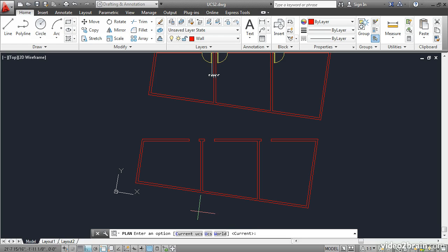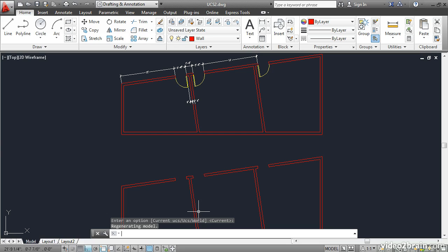We're going to go to the current UCS, which in this case is the WCS. So simply press Enter, and the geometry is reoriented with respect to the WCS. So to summarize, you practiced drawing in a UCS aligned to an area of interest, switched back to the WCS in the end, and used the Plan command to match the orientation of the viewport to the current coordinate system.